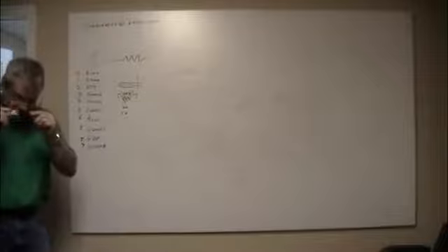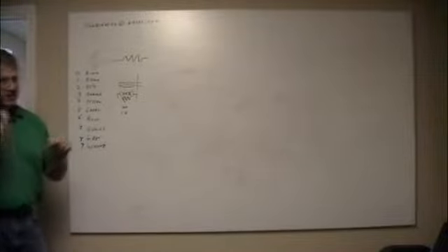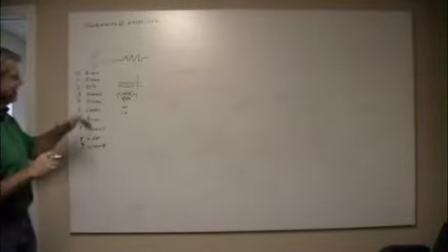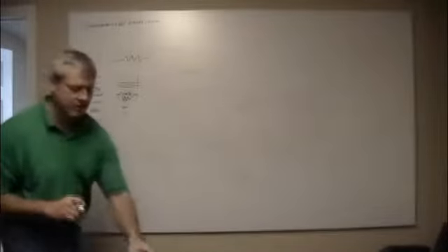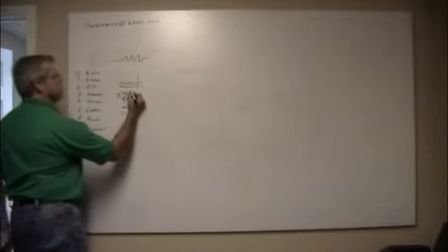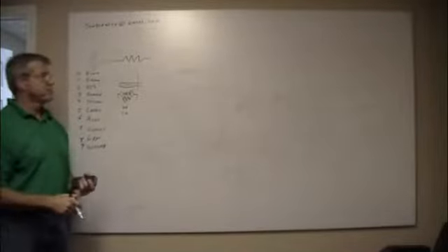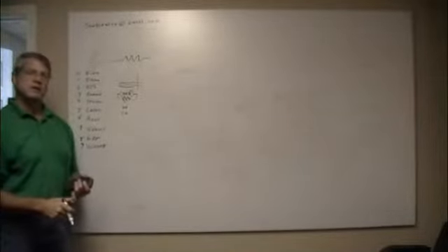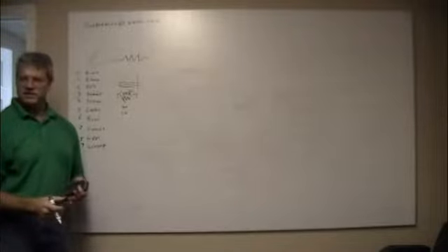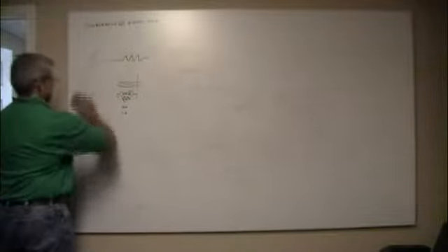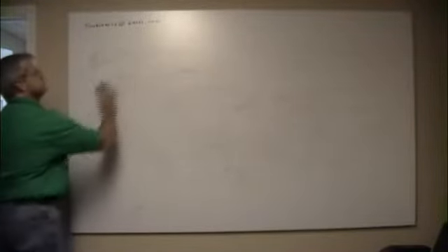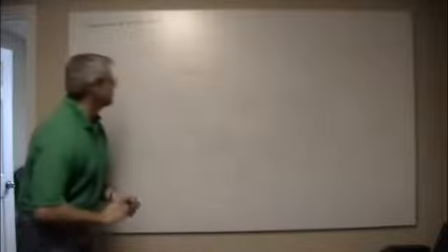Most of the time, they don't have the bands on there. You might look at it, and it might have the number actually stenciled on it if you've got a magnifying glass. So I don't use them anymore. Oh, and then these bands would be tolerance bands. So gold was a 5% and silver was a 10%, or maybe it was a 1% and a 5%. I don't remember. So, history stuff that you probably don't care about too much.